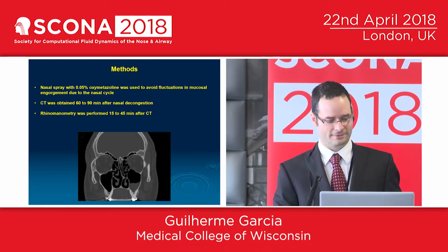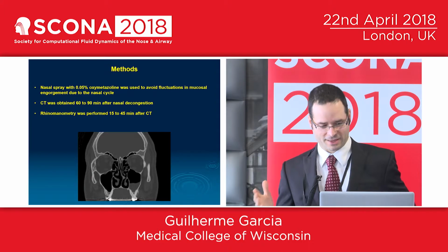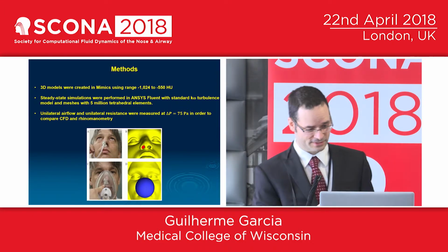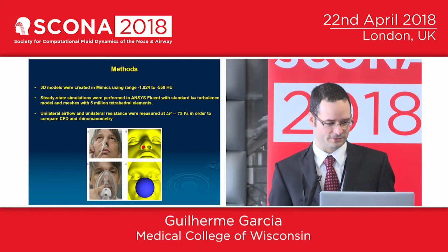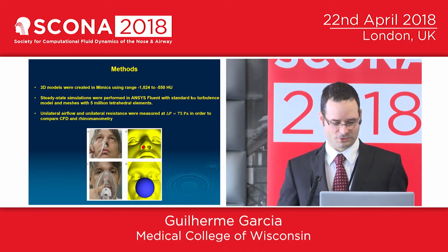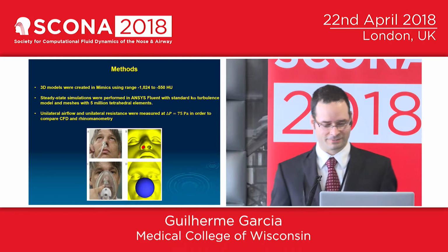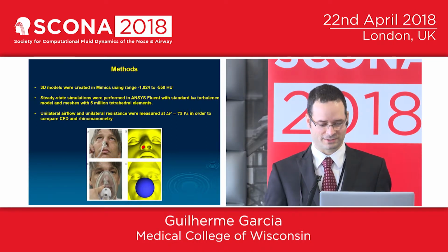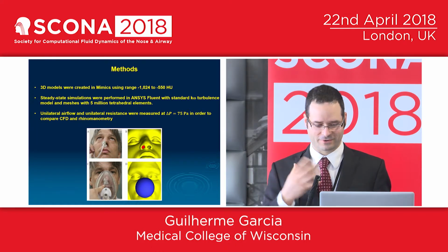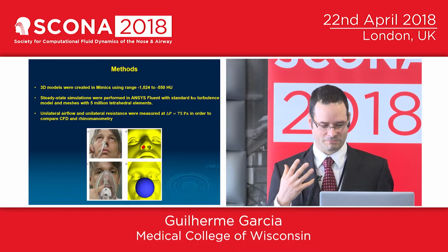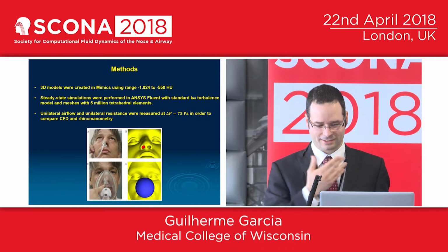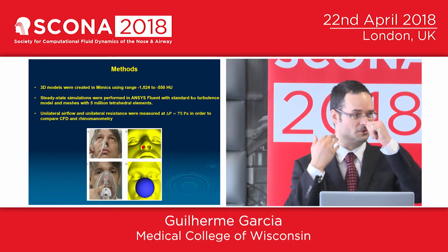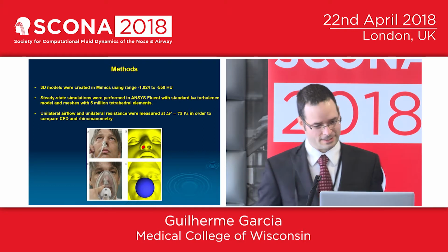Then rhinomanometry was performed about half an hour after the CT. So this is actually the main author here, Dr. Querubim, showing how the rhinomanometry was performed. And for the CFD, we reproduced the rhinomanometry. We had this air ball in the front to have the inlet boundary conditions, and we closed one nostril at a time so that the flow would be unilateral.